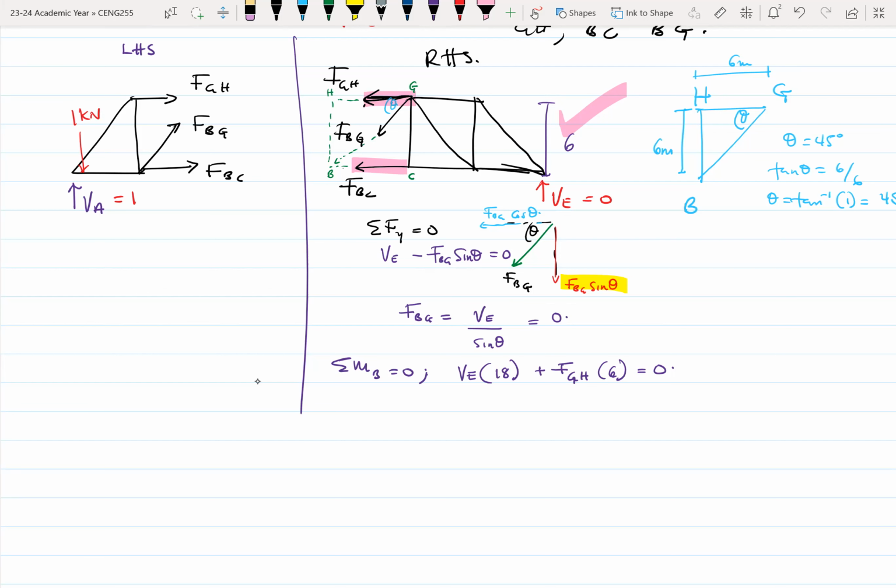But the distance on the deck can vary. It depends on how the deck was designed. Normally, trusses are designed to have the same spacing throughout, for convenience of construction and all of that. It also makes the design fairly straightforward. But it's not always the case that you have the spacing between the vertical chords being the same. I've seen bridges that have different spacing, so just take note of that. In this case, yes, but sometimes it can vary.